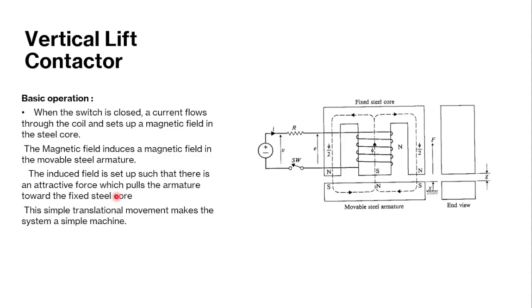And yes, this is a magnetic circuit. If you look at the core or the flux path, it goes in here, splits left and right, goes through here, through our air gap, and comes around. So it's still a magnetic circuit. It just has an air gap in it. So the air gap will be part of the flux path.